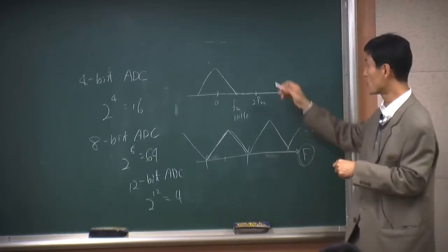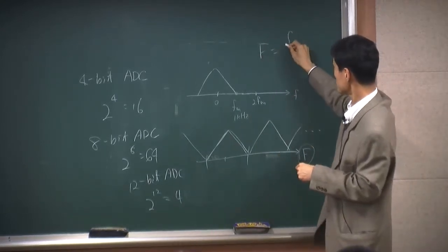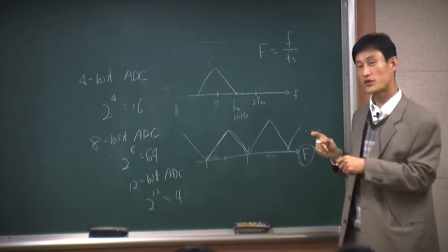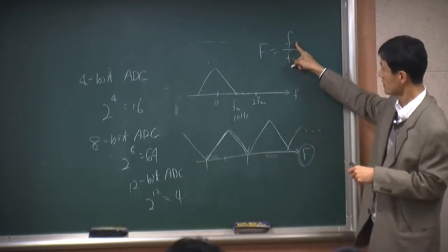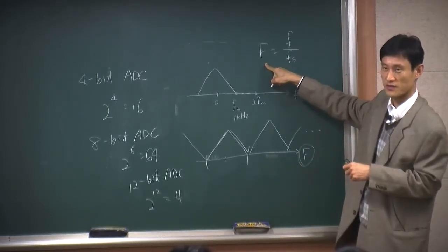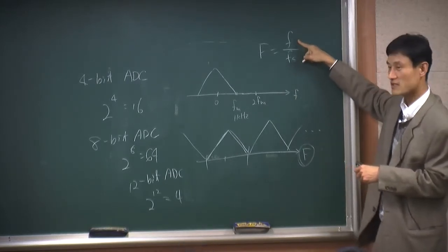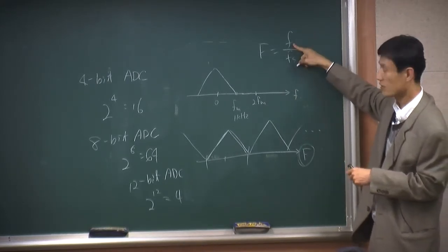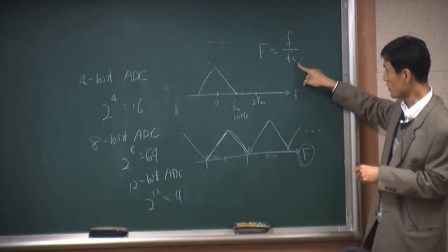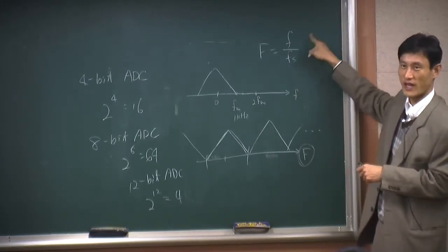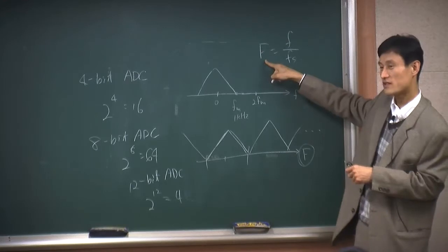You do a normalization, right? That's what you do. That's analog frequency, change it to the digital frequency. So you divide by sampling frequency. So the original frequency is like hertz, like 1 kilohertz. Sampling frequency is also like 2 kilohertz. So you cancel out. So digital frequency has no unit.